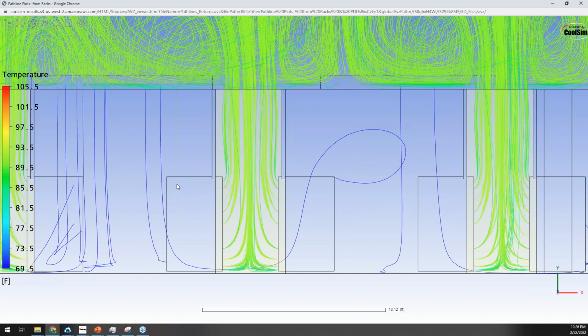So have a look. Here's what we have going on: air coming out of these servers very, very fast. It's hot. Remember, they're blowing this pretty hard to each other. Now, we remember from our friend Bernoulli that total pressure is the sum of static pressure plus dynamic pressure. As this air comes out and it slows down because they bump into each other, they hit each other. As they hit each other, the velocity drops, static pressure rises.